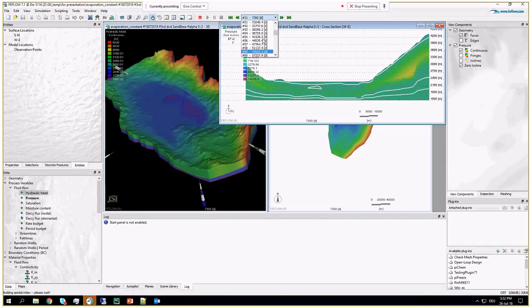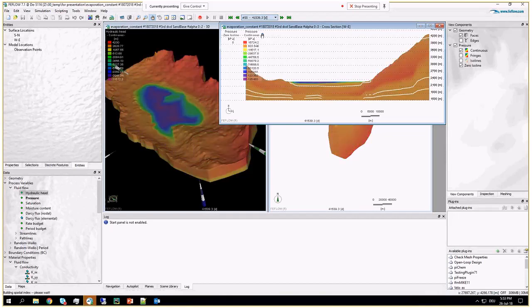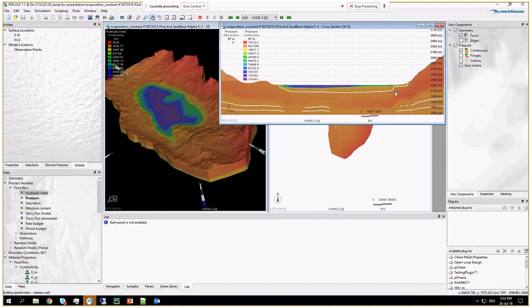I will just go farther in the simulation here. So the water level is also stabilizing. Here we have a local water level system and there is a strong decrease of hydraulic heads here. The elevation of the model is about 4,200 meters and here it is about 1,500 something, no? So here you have negative hydraulic heads. We are solving an unsaturated problem. We solve Richards' equation and we have an empirical definition for the unsaturated parameters. We use modified van Genuchten parameters here.